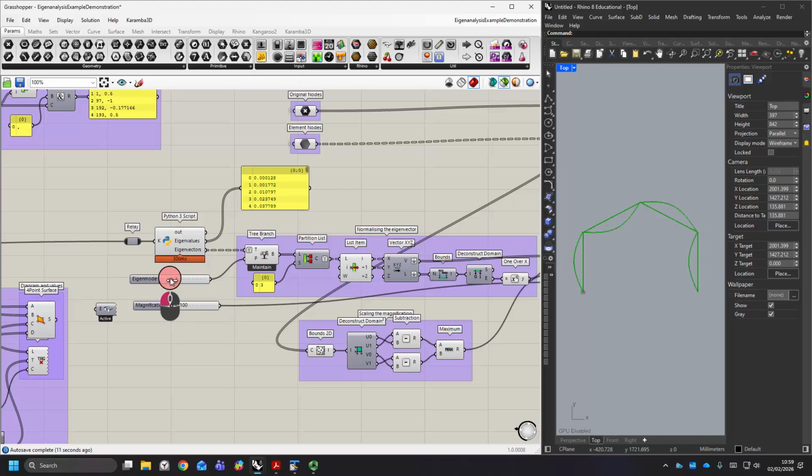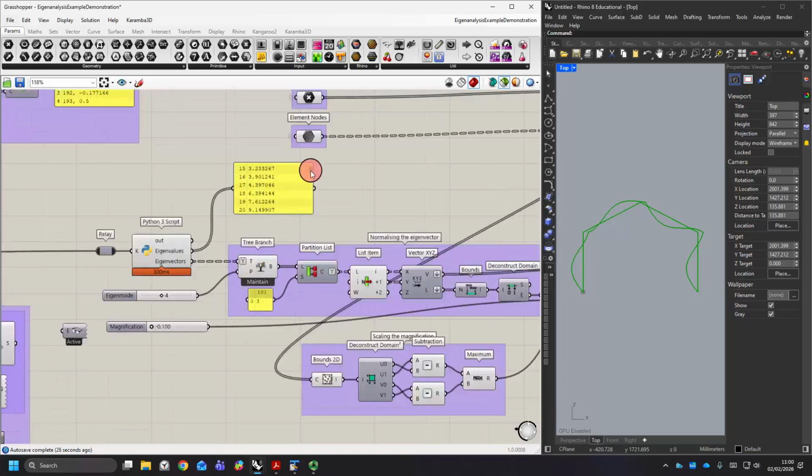And then as I run through these, we get some sort of increasingly less likely deformation modes, and you can see these are associated with increasing stiffness values. So once we're up to the value associated with, say, 10 or 11, we are several orders of magnitude higher in terms of the stiffness mode, and you can see that the potential displaced shape is getting increasingly unlikely. But it is a useful check.